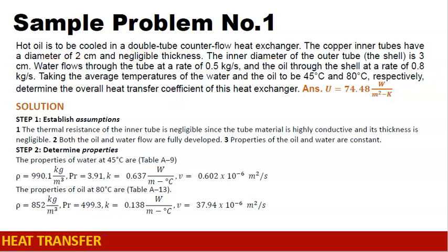So the first thing that we should do is to establish our assumptions. For this problem, our assumptions are: the thermal resistance of the inner tube is negligible, such that we will not consider conduction, because this is a tube with negligible thickness. Both the oil and the water flow are fully developed. So properties of oil and water are constant.